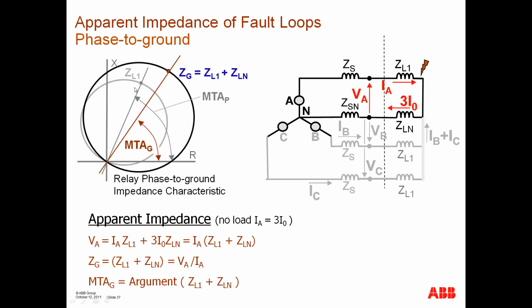So that is a term that has grown in the industry that represents either the line angle, or it could be the maximum torque operation for a directional unit, where the maximum closing torque or maximum opening torque or restraining torque is produced at a particular angle.